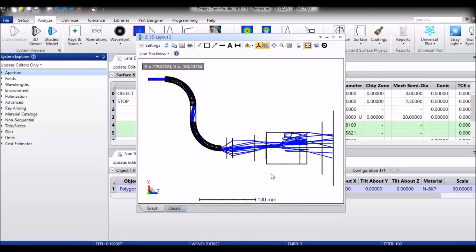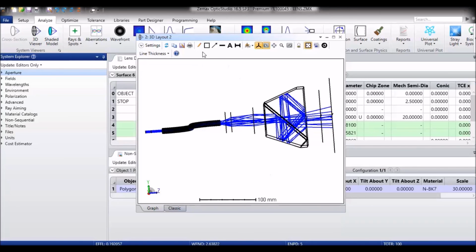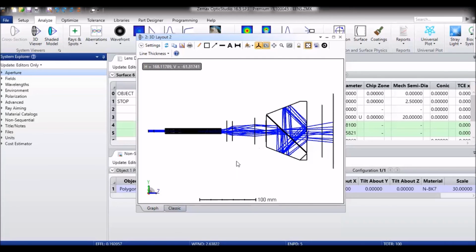This view is a little bit confusing because the prism's not upright. Let's tilt it up a little bit, and let's actually use this YZ view. You can now see the prism behavior where rays hit the air gap reflectively, then transmit through here and again reflect off here until they hit the image plane. And if you update, you can see that this is now a nice non-sequential behavior within a sequential group.